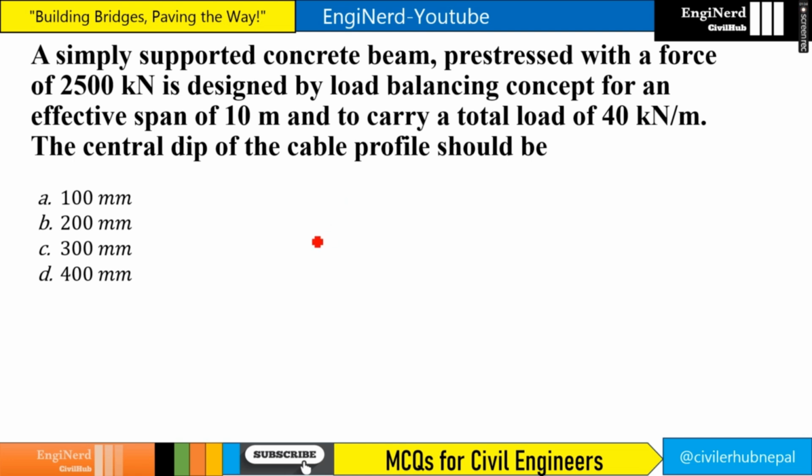Now, a simply supported concrete beam pre-stressed with a force of 2500 kN is designed by a load balancing concept for an effective span of 10 meters and to carry a total load of 40 kN per meter, right? So in the case of parabolic, H equals WL square by 8P. You can also derive this, but I am writing this directly. So H equals WL square by 8P.